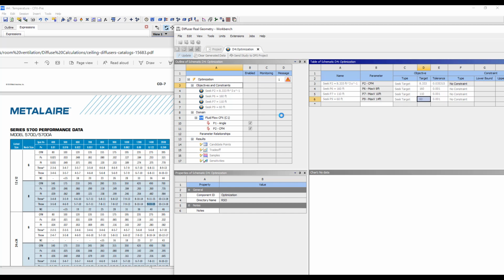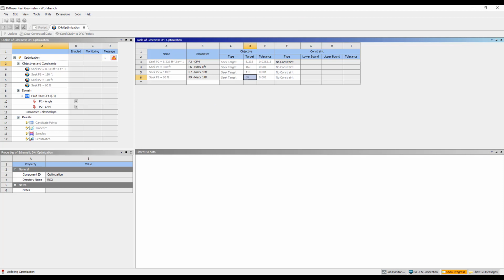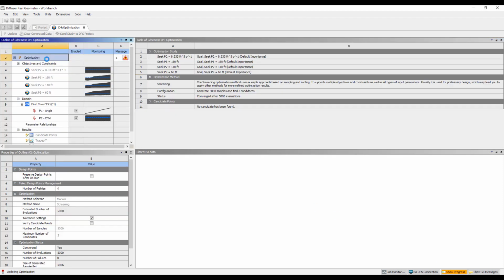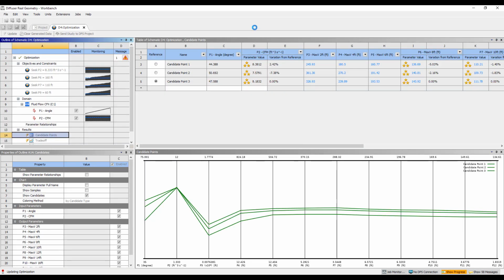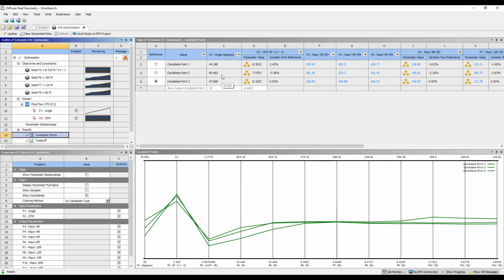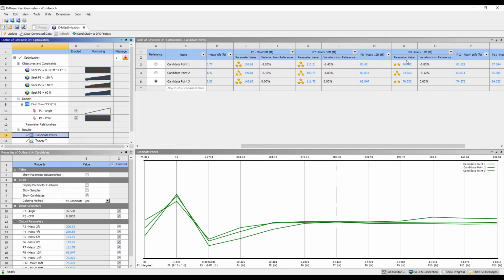Just go ahead and do an update, and Ansys will kind of extract 5,000 potential designs from my data points and calculate a response surface for me, a candidate point for me. And it gives me 3 options. So it says you got everything from 50 to 47 to 45. And if we look at the parameters of interest at 8, 10, and 14 feet, we want something in this range.